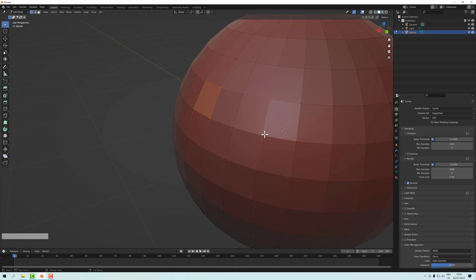is not necessarily all that fussy about how you've selected a polygon. If you then activate a polygon tool, for example extrude or inset, it will act on the polygon you have selected. So even if you're in vertex mode, you can then go inset. Let's do that.